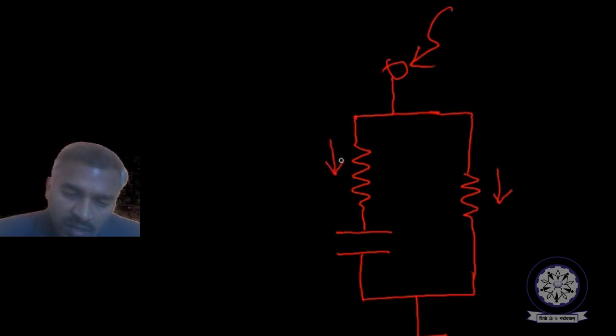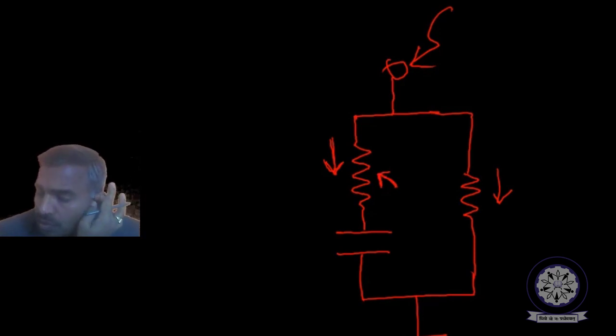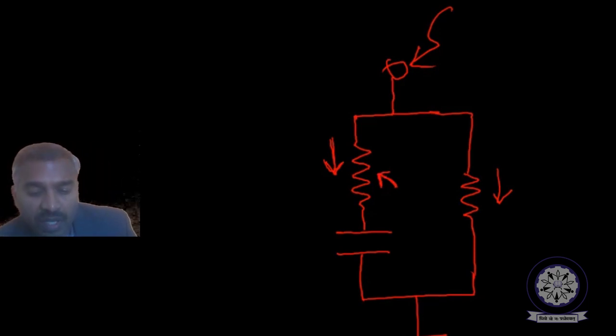Now, in this case, these are actually leakage currents or lossy currents, and this is displacement current only, polarization current. But this resistor represents the losses due to the AC component of the current. So this kind of complex network representation for a lossy capacitor is also possible.